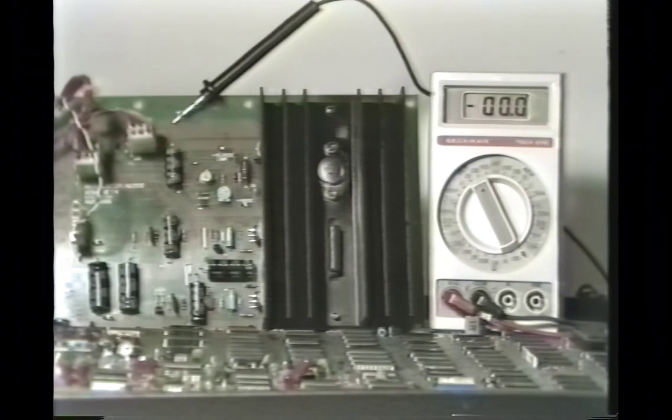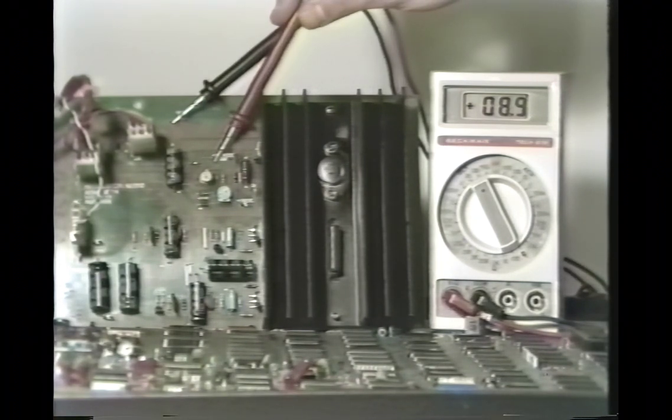Knowing this, and based on the incorrect assumption that the problem is low voltage from the regulator, our average mechanic then checks the input to the regulator and finds it to be slightly under 9 volts DC. The average mechanic's no fool, and he knows as long as he has at least 7.5 volts as an input to the regulator, the output should be a constant 5 volts. Since he's tested the input and he has at least 7.5 volts, and he doesn't have a good 5 volt output, he assumes the device to be bad and changes the regulator.